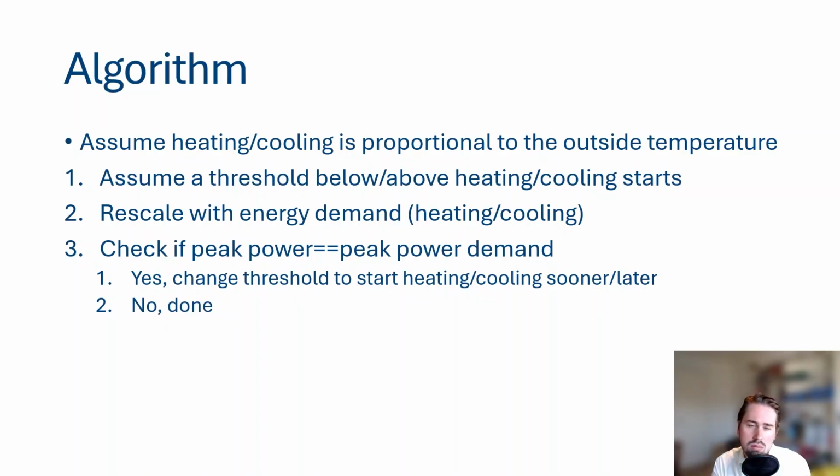So this is how you would do it for a single building. But for collective buildings, we have this simultaneity where, for example, our installed peak power is not really our peak demand. Because, as we said, depending on the orientation, etc., the resulting peak power for the collective system is smaller than the sum of each individual building. And with these three steps, you get the theoretical demand profile of the entire building.